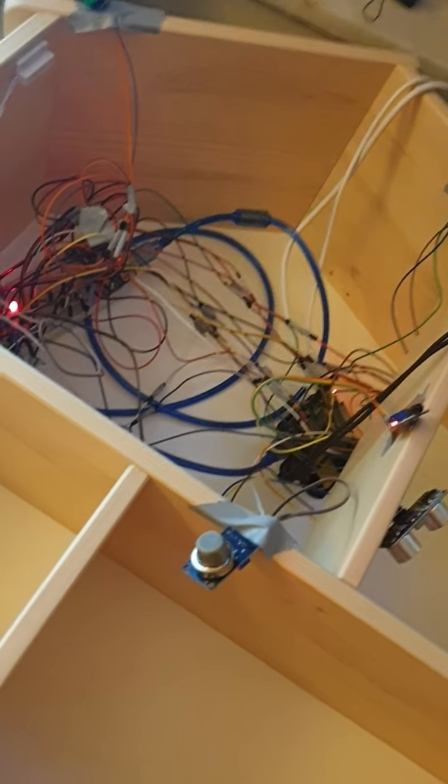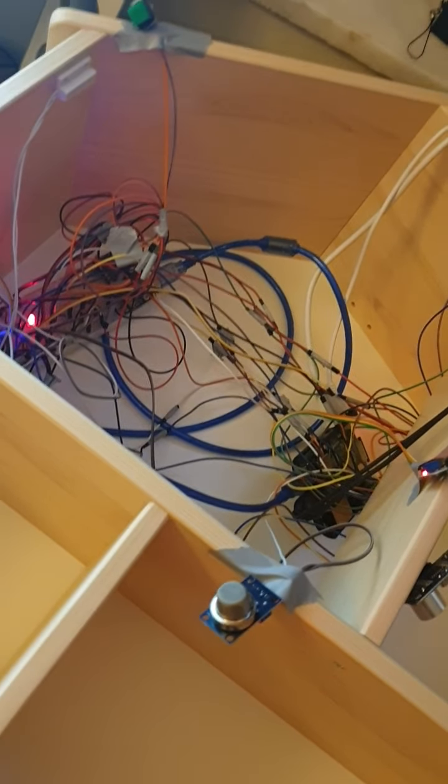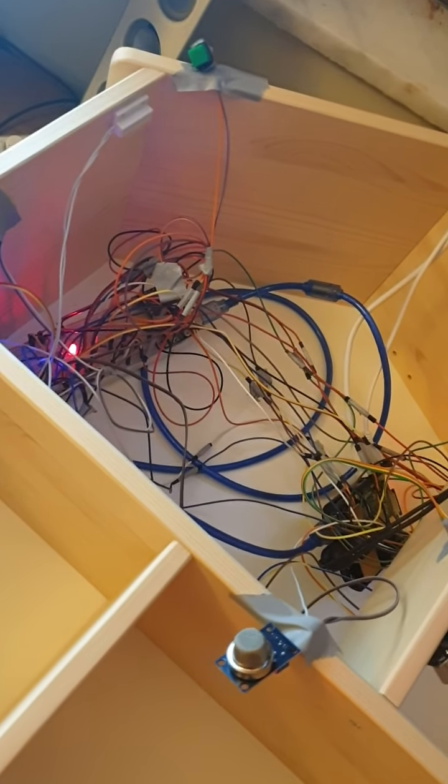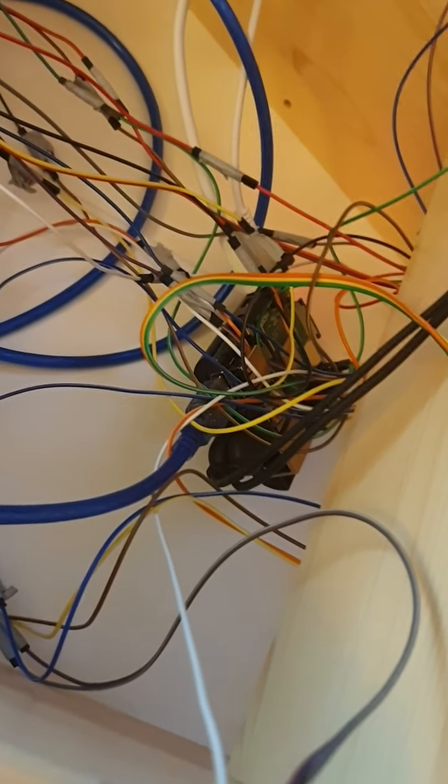Hello, my name is Nikolaos Sisifidis, and in this exercise an embedded house automation application has been built and programmed. The system is based on a Raspberry Pi 4B device, which offers a 4-core CPU, 4 GB of RAM, a complete and multitasking operating system, which is Raspberry Linux, network connectivity and Wi-Fi, and 28 GPIOs which support interrupts and special functions such as PWM.